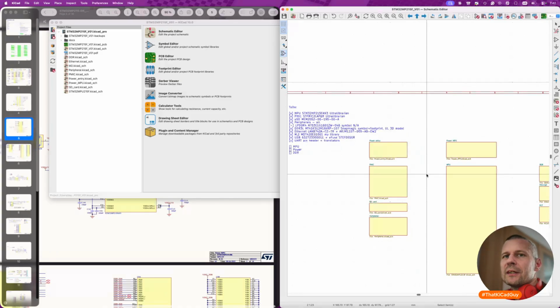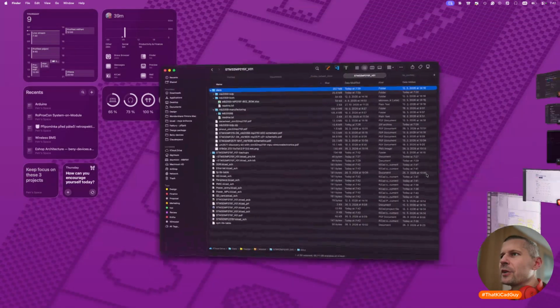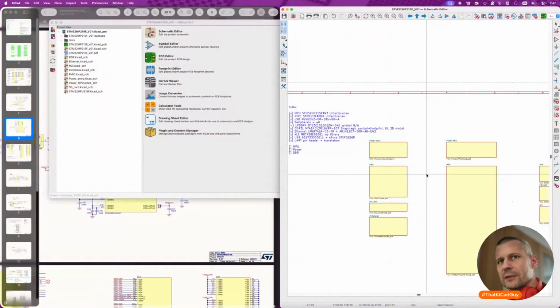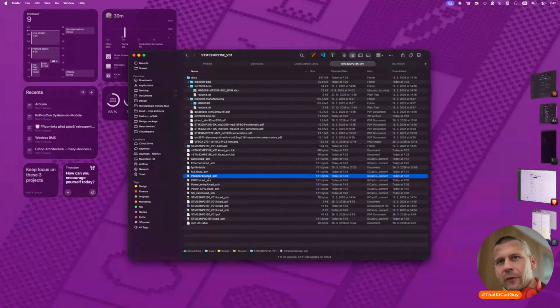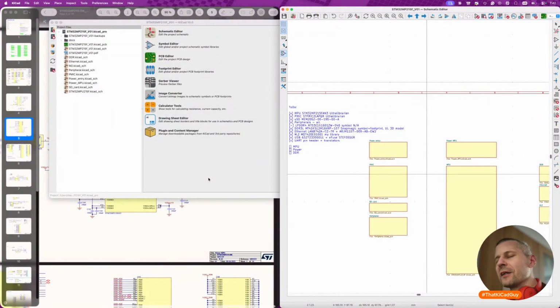Sometimes I do the changes in the file manager and then get back to KiCad, because then it's easier to rename the file here, and I'm 100% sure that the file is the same as before the renaming. When KiCad renames the block, it can happen that it deletes the old one and creates a new one. I don't know how to avoid it. I don't know if it's still an issue in this current version, but in the past I lost some schematic block once or twice.